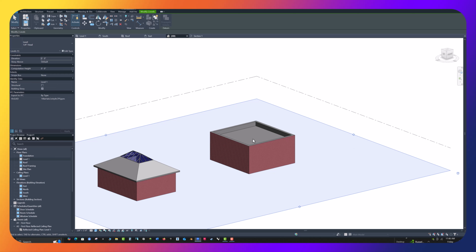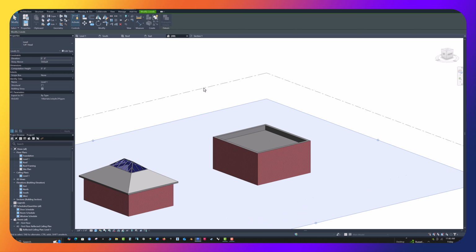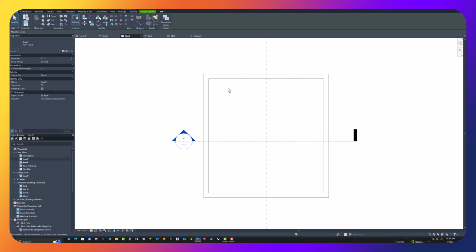So now I need to add some way to drain this roof. So I'm going to go back to the roof again. And I'm going to tab select until I get my roof. And there it is. I'm going to select it. And in the ribbon now, I have something called shape editing. And this allows you, for both floors and roofs and for topographic solids, to change the shape of the object by modifying sub-elements. And I'm going to click on Modify Sub-Elements.